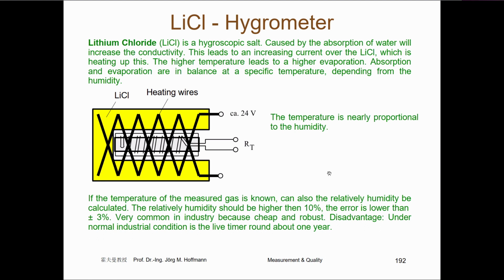But very cheap is the lithium chloride sensor. This lithium chloride is a salt, a hygroscopic salt, and you see here this material where a liquid with the salt is in, and then you have here two wires which are not connected.